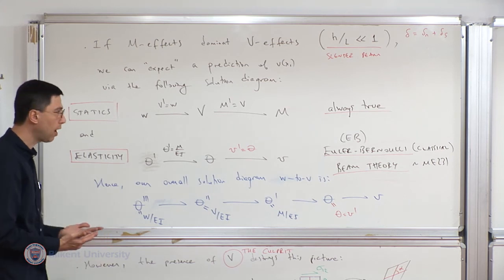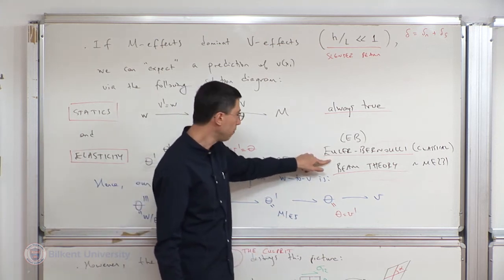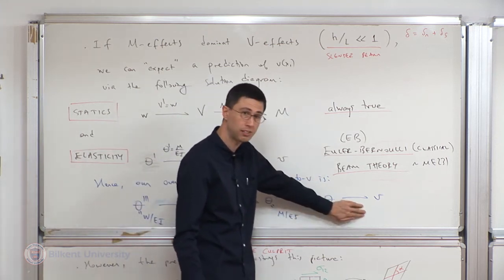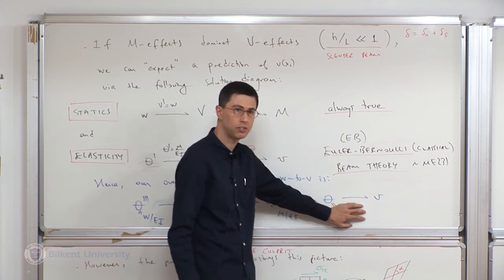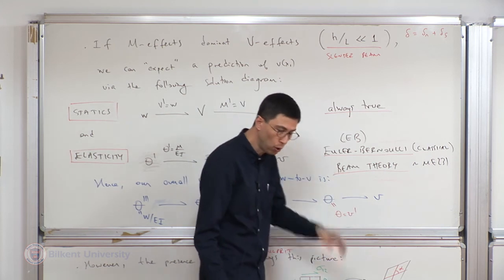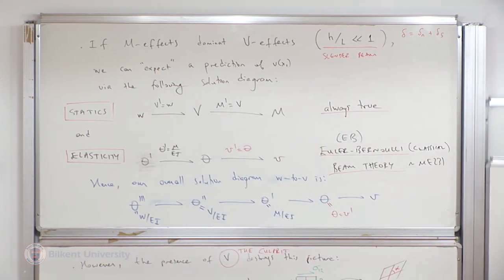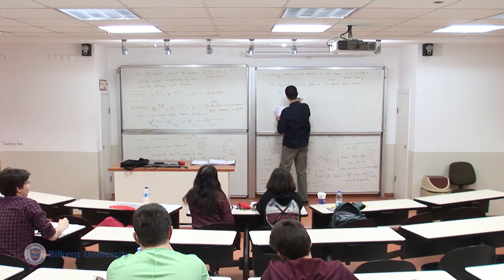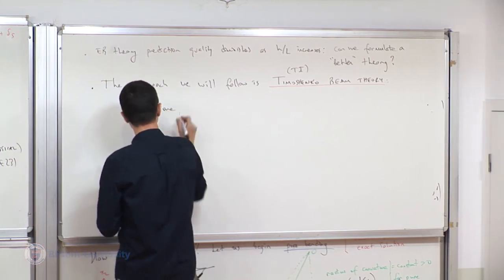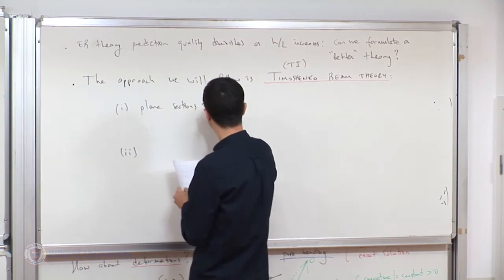In this way, I'm going to take a step beyond the earlier Bernoulli beam theory. It means that I do not make this assumption, and I have to assume something else. I don't know yet what, but I will make that assumption. So let me write those statements. I will still assume that plane sections remain plane.